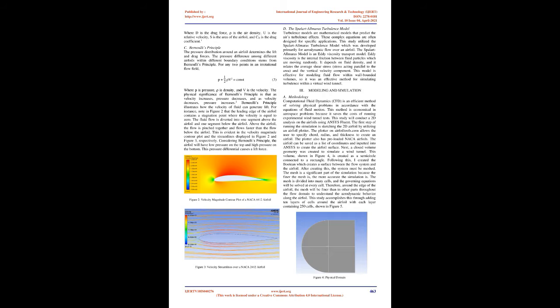B. Lift and drag analytical solutions. As an airfoil moves through air, air exerts both lift and drag force on the airfoil. Lift and drag forces are caused by wall shear stresses and pressure stresses. Wall shear stresses occur tangential to the airfoil surface, and pressure stresses occur normal to the surface. The lift and drag coefficients are valuable components of the lift and drag forces. The lifting force generated by an airfoil depends on density and relative velocity. The force is also dependent on airfoil shape, angle of attack, and air density. These three variables are embedded in the lift coefficient.